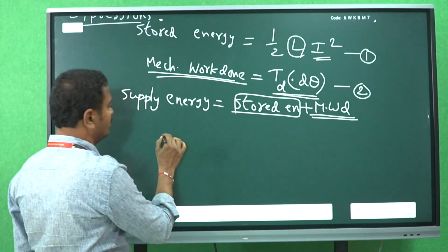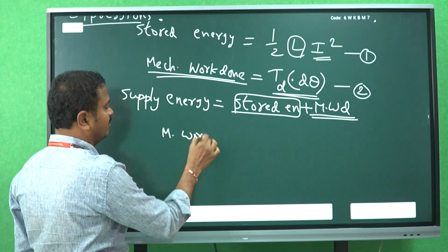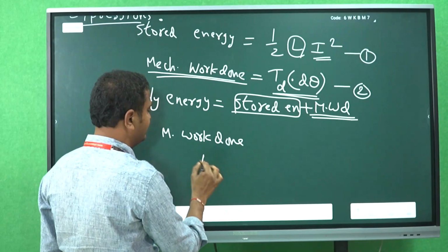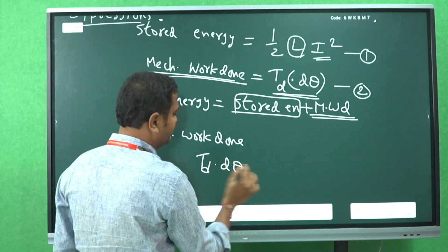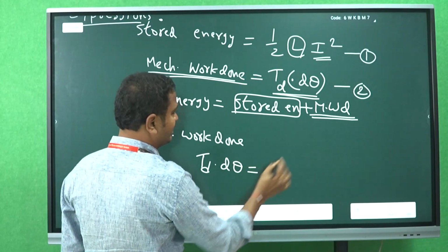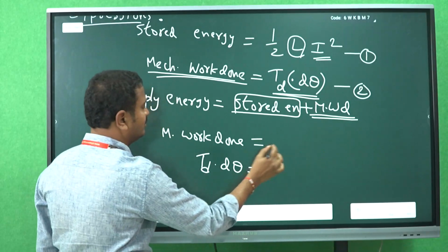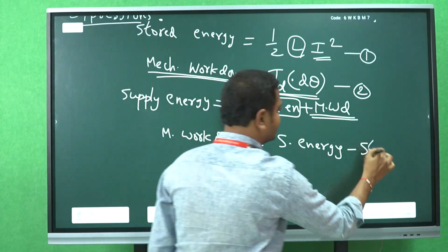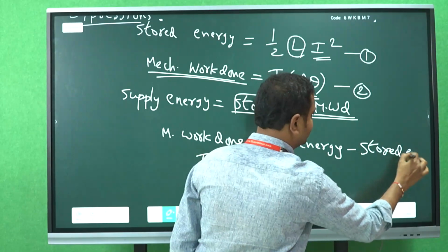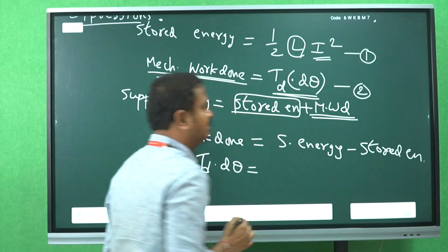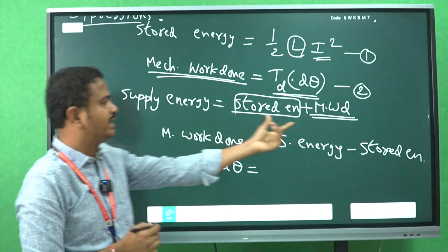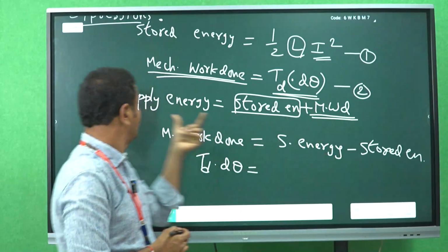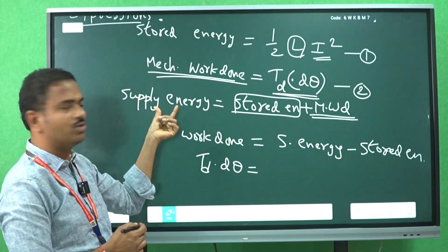Clear? So mechanical work done is Td d theta, which is equal to supply energy minus stored energy.